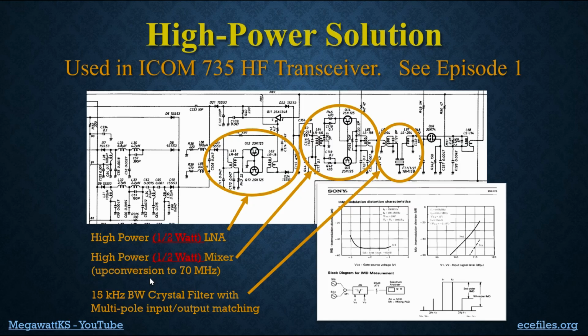Well, you can go back through those formulas. Let's see, 1 watt versus 10 milliwatts. That's a factor of 100 in power. That's 20 dB. So it's going to change your input third-order intercept point up about 20 dB. It's a high cost, right? I mean, we're burning a watt to get up 20 dB.